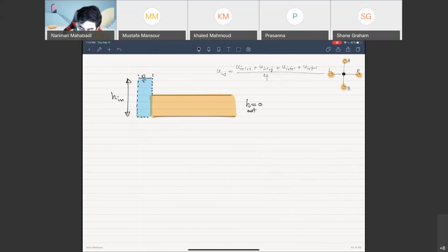Okay, so let's see how we can actually solve this Laplace equation for this simple problem. Let me create a grid point along my domain. My domain is just inside my soil, right? I don't care about this tube. This will just give me the information of the inlet total head. Let's see what we have.